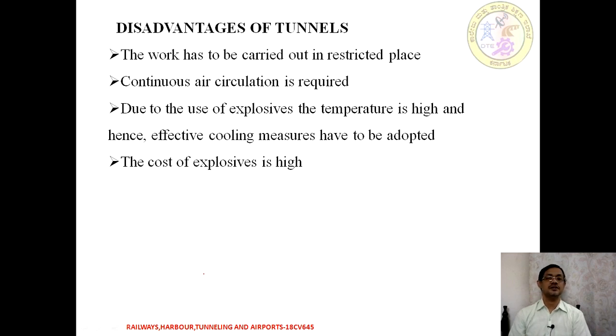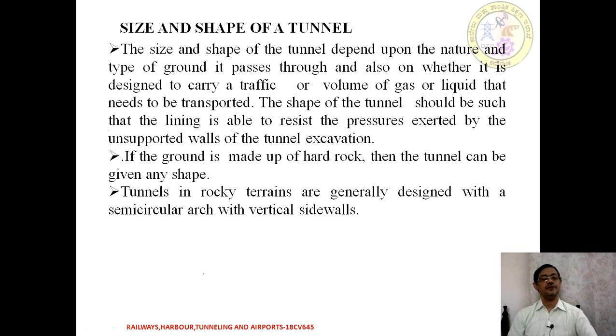The work area is restricted, and continuous air circulation is required as we are going to be using some explosive. The temperature is going to be higher, hence effective cooling measures also have to be adopted, hence the need for ventilation and circulation. The cost of maintenance and construction is higher, and the cost of explosive is also higher. So, we have used the term tunnel, and seen the advantages and disadvantages of a tunnel and why we use it.